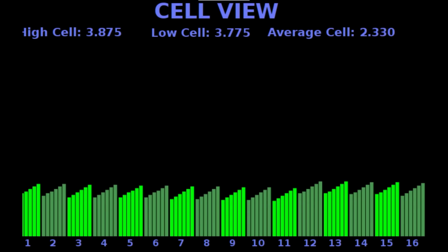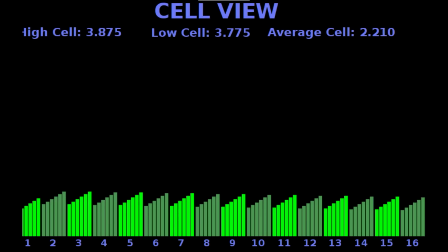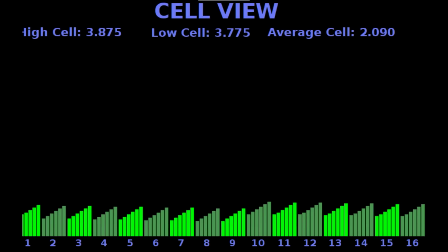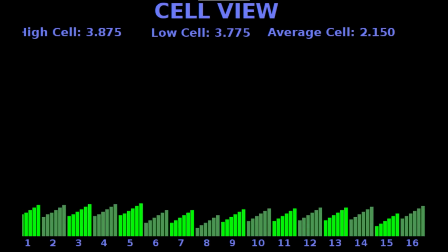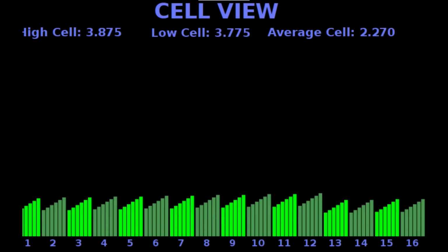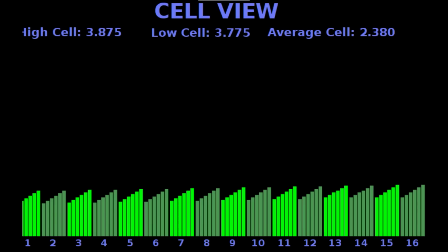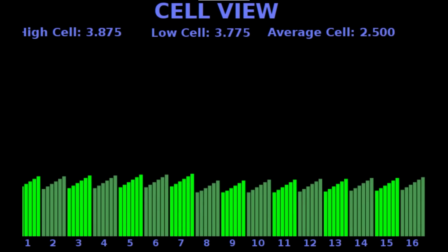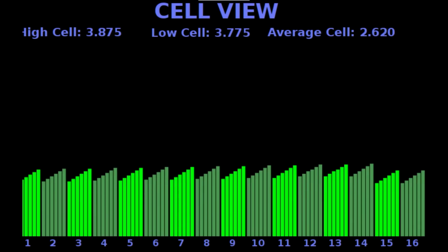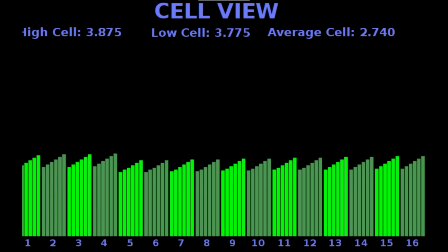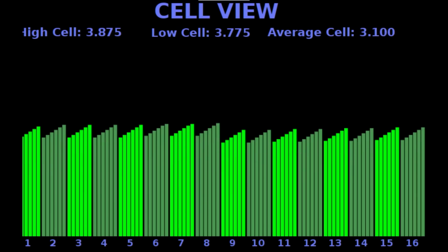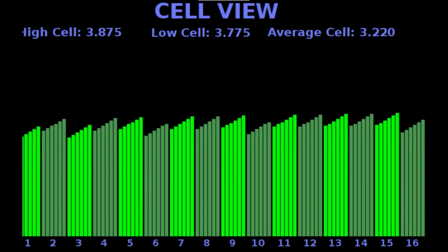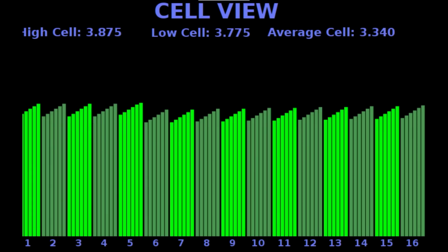Well, this is ideal for UDP. It's connectionless. It's like CAN, and a lot of packets get stepped on or just get lost. Your AP's doing other things, and both your devices are doing other things. But you can see in the cell view as it sweeps across sequentially, and we're doing pretty good right now, but here we missed one. And you can see sometimes we're missing packets. Here's one here that it just didn't get updated. Well, it'll catch it on the next sequence.